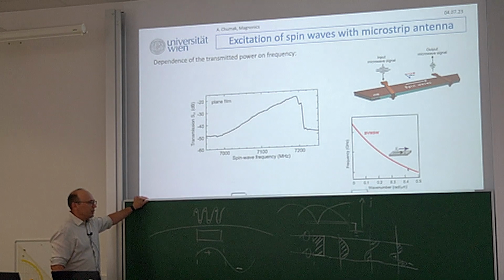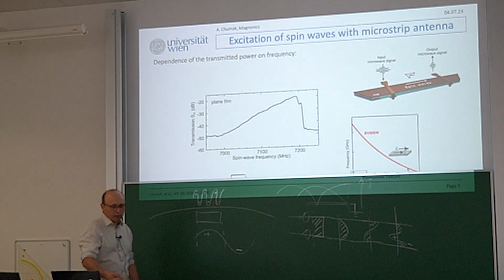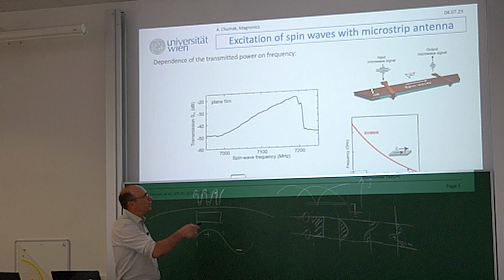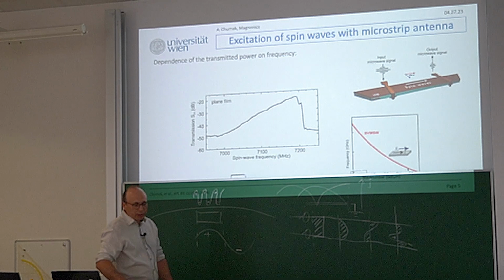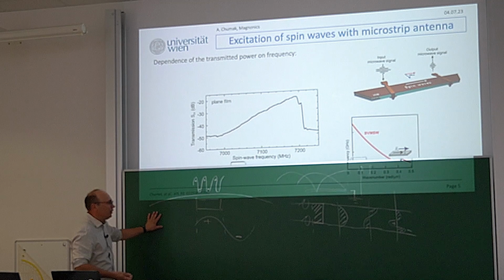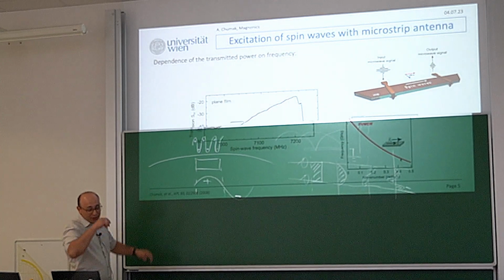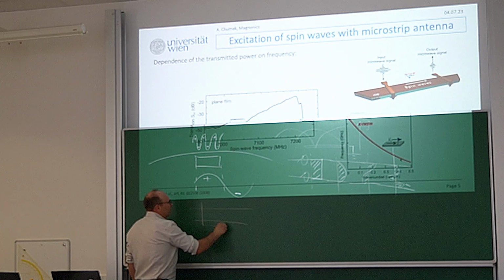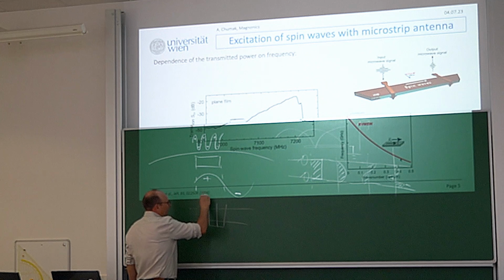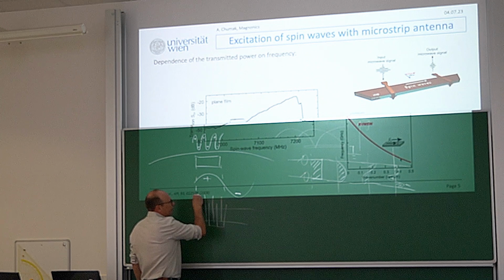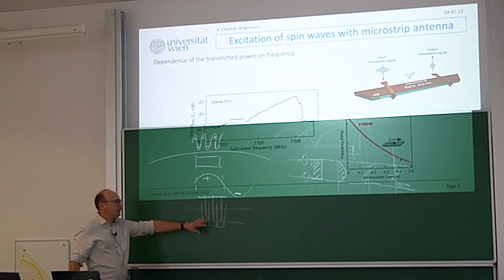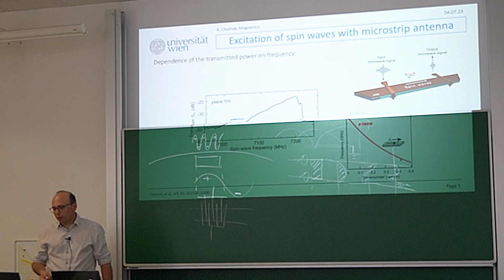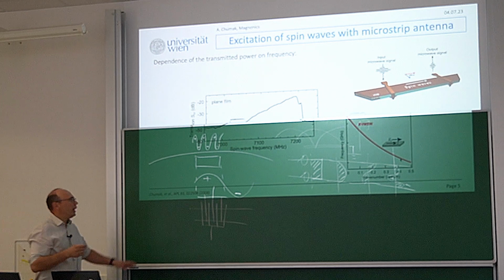So the question of Rostislav is whether we can improve excitation efficiency if, instead of having this absorber, we put a 90-degree cut and kind of a mirror. Yes, it should. I always wanted to try it, but never did yet. But we will, because if you go to surface acoustic waves, they have these finger-like antennas, and because you need to apply an electric field here, they then excite the surface acoustic wave. It's very good, with high efficiency of excitation. That's why each of our smartphones has tens of such filters, and